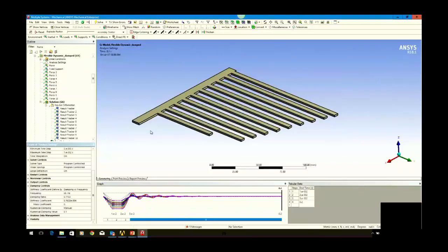You can put a constant damping ratio across the whole frequency range, but in general at higher frequencies the damping ratio will be higher, because of this stiffness coefficient. It's normally a constant value, but you can base it off a certain frequency, or if you want to damp out a particular frequency, you can do it the opposite way.